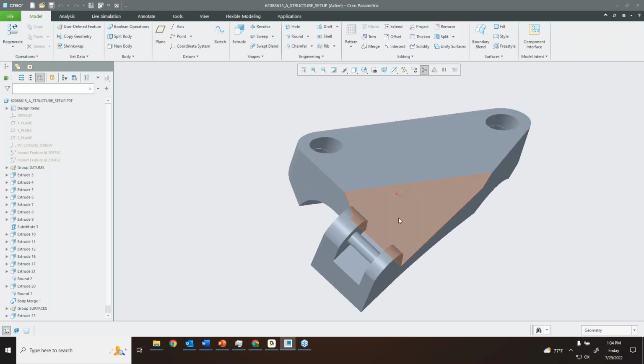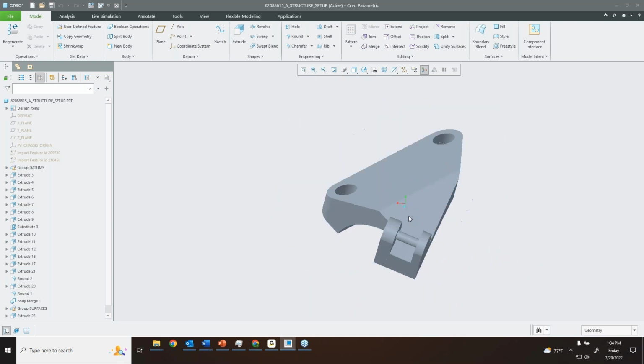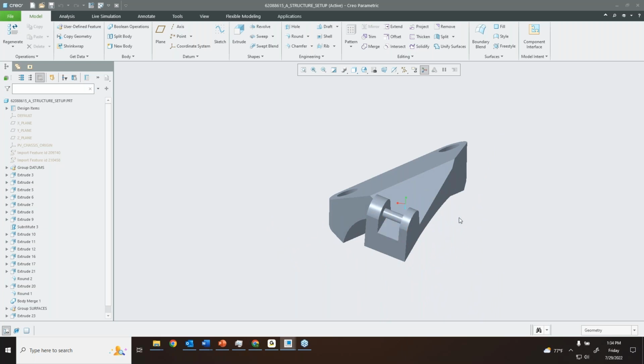And before we get into the actual GDX extension, I'm going to utilize one of the new features that we talked about in part 1 of the Creo 9 improvements, this surface divide. So I'm going to divide a surface on here that we're going to use to apply the load during our GDX, or our generative design.